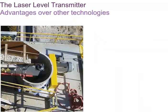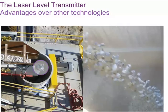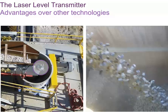One of the characteristics of lasers is that the light beam is narrow with virtually no divergence. This means that the laser level transmitters can measure in tight locations. The laser level transmitter is capable of measuring the level of a surface at any angle. The laser level transmitter can be configured to ignore sudden changes, such as occurs when a rock interrupts the beam.